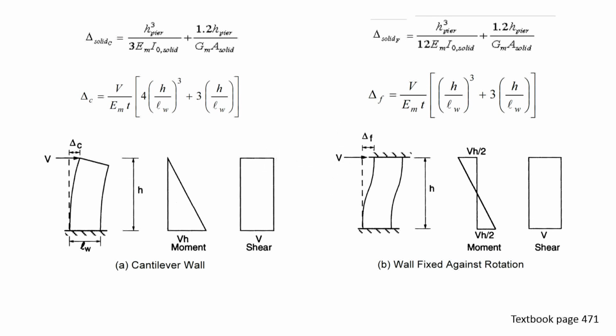Now, by applying simple beam theory for elastic sections, we can approximate this for a rectangular cross-section, which we use to represent our masonry walls. There are 2 components of this total stiffness. We have the flexural and the shear component of that. So this process is simplified by limiting the loading and boundary conditions assumed by our walls, we can only look at the top as being fixed or as being fully cantilevered.